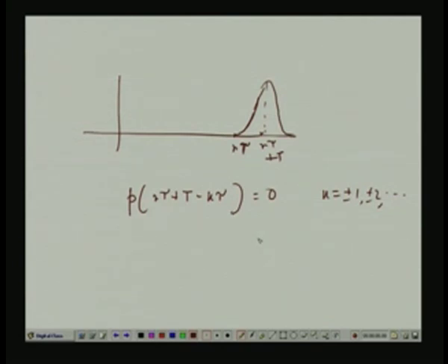The pulse we have shown does not follow this zero forcing condition, but look at this pulse. Suppose this is your center point and this much is tau, this much is tau, like that. As you go to the left by tau, 2 tau or 3 tau, or to the right also by tau, you have 0 crossing. So this will ensure that there is no intersymbol interference. We design such pulses, and these pulses are called Nyquist pulses.